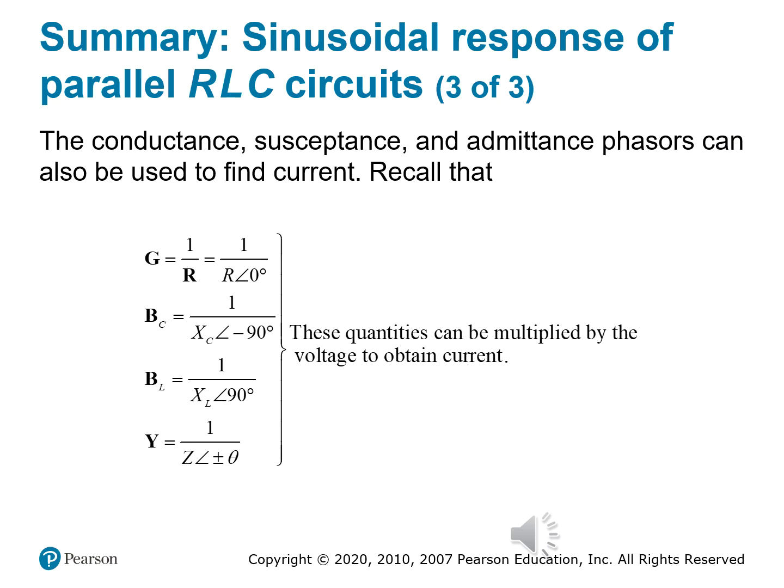And here's the insight for this slide. Once you have these admittance values, you can simply multiply them by the voltage to get current. That's right. So we're using Ohm's law, and Ohm's law carries on, but now in the reciprocal form.